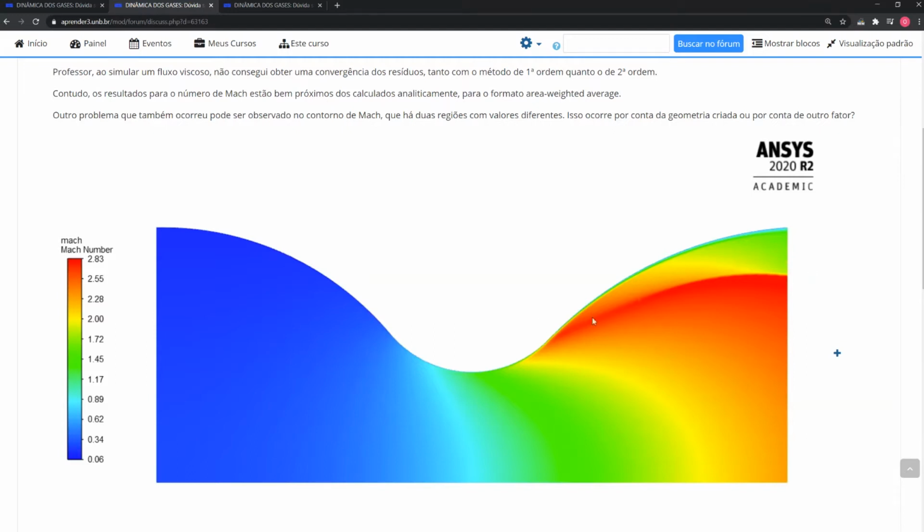It's the problem from the optimal flow, of course, because the nozzle is not isentropic and the losses will happen. But from the point of view of your calculation, there is absolutely no error. Flow is expected to be like this, and if you start to optimize the supersonic shape here, you can decrease this region of low velocity. You can decrease the strength of the shock wave in this region. It means decreasing the drop of the velocity here and the rise of pressure. And you can improve the characteristics of the efficiency, like stagnation pressure ratio.